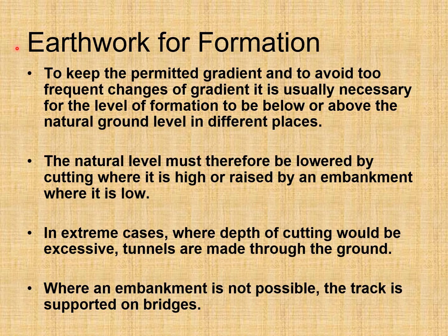Earthwork for formation. To keep the permitted gradient and to avoid too frequent changes of gradient, it is usually necessary for the level of formation to be below or above the natural ground level in different places. The natural level must therefore be lowered by cutting where it is high or raised by an embankment where it is low.